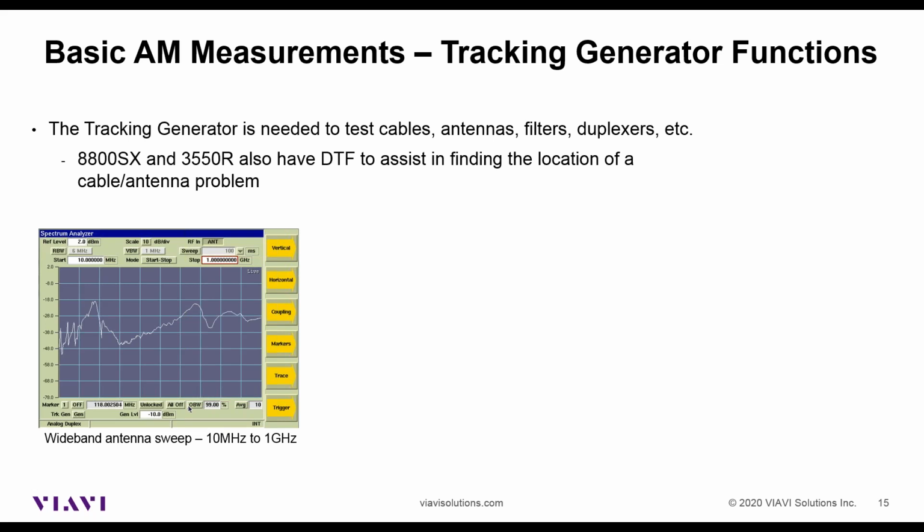Actually, what I've done here, I've got two identical antennas and I've placed them close together. If you wanted to, you could use a VSWR bridge and measure just a single antenna, or another way to do it, which is not perfect but it's reasonable, is to have two golden antennas.